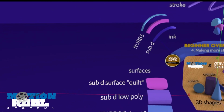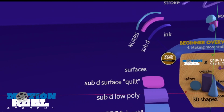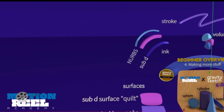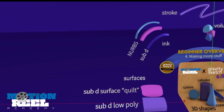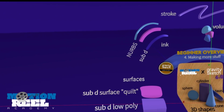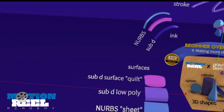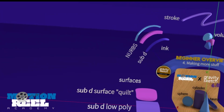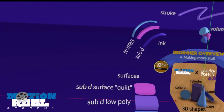NURBS modeling is more for architectural work and solid modeling. The other thing you have to consider when you're working with NURBS is what software you'll be working with after Gravity Sketch. If it's CAD software, then you'll be using NURBS, and when you bring it into the CAD software, it will render and be editable. Sub D is more for organic style modeling, although you can model hard surface with Sub D.